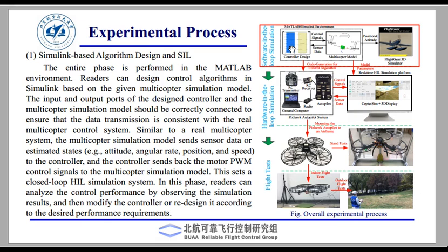Similar to a real multi-copter system, the multi-copter simulation model sends sensor data or estimated states to the controller, and the controller sends back the motor PWM modulation control signals to the multi-copter simulation model. This sets up a closed loop. This system is not hardware in the loop, it is SIL, software in the loop.